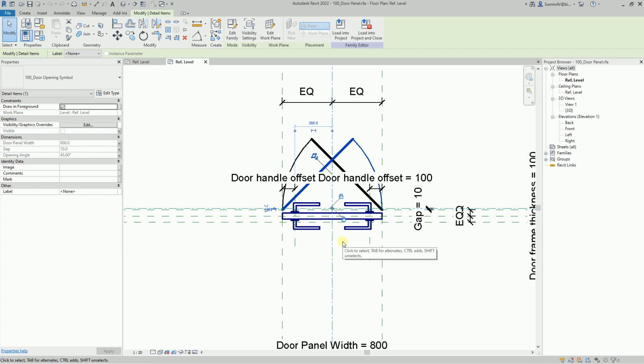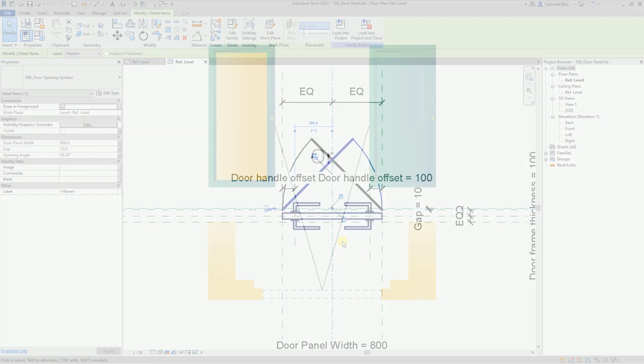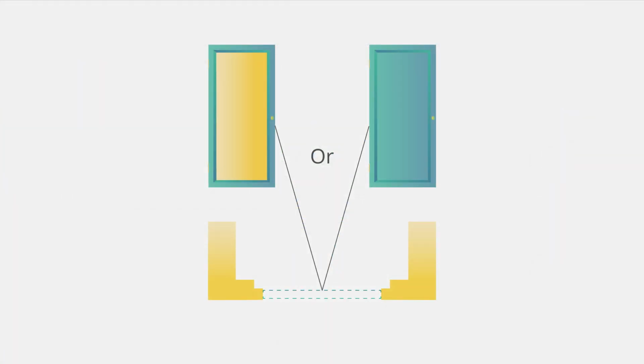The fourth situation we use nested families is when there is a certain component inside of the parent family, at the position of which we would like to place one or another object by choice. For example, our door family may have several different nested panels, and we can select one of them through the parameter. Let's consider such a situation.